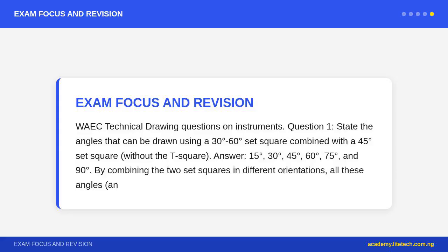Question 4. A drawing is made at scale 1:50. If a wall is 4.5 m long, how long is the line drawn for it on the paper? Answer: 1:50 means 1 mm on paper equals 50 mm actual. Wall length equals 4.5 m equals 4,500 mm, line on paper equals 4,500 divided by 50 equals 90 mm.